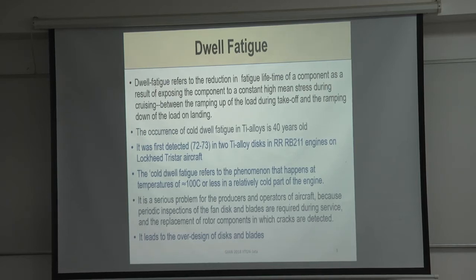Here I wrote again, cold dwell fatigue refers to the phenomenon that happens at temperatures of approximately 100 degrees C, but more like 120 degrees C or less, in a relatively cold part of the engine. And we're talking about titanium alloys here, not aluminum or something. That's a pretty low temperature for titanium, right? 120 degrees is quite low for titanium.